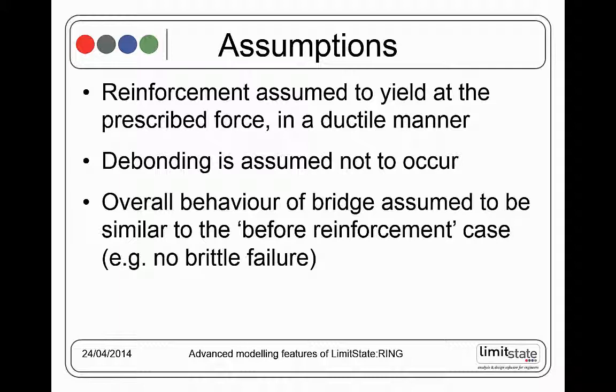So we're not allowing complex, particularly brittle, punching shear type failures to occur, simply because the software is based on plastic analysis principles, and clearly such software is not appropriate for doing analysis of a brittle phenomenon.